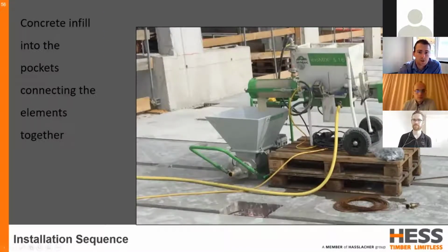So then infilling of the concrete blocks was undertaken after the floors were installed, and these were the only wet trades on site, obviously outside of the main in situ cores, and there was no requirement for any backpropping. So the wet trades could be taken off critical path, as by the time the grouting cured, they were spending time on the other segments of the floor. Remembering that there were five segments which docked to the main cores, which meant that they didn't need to get held up by wet trades.